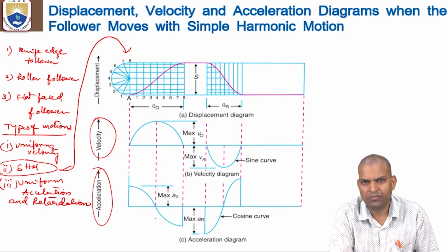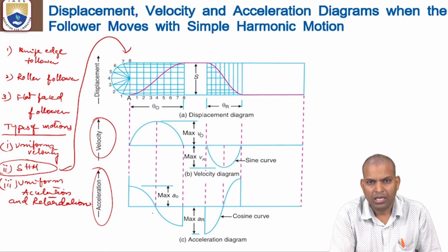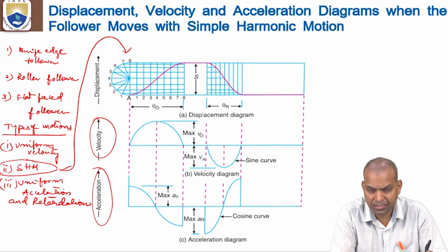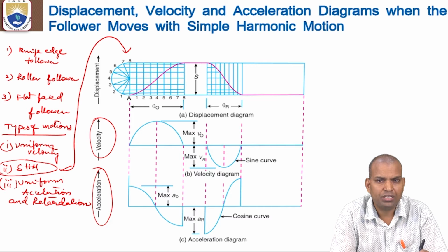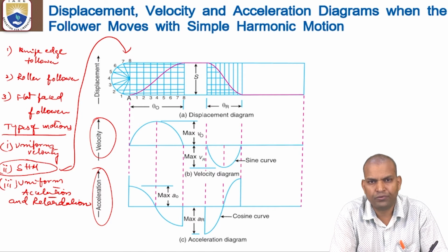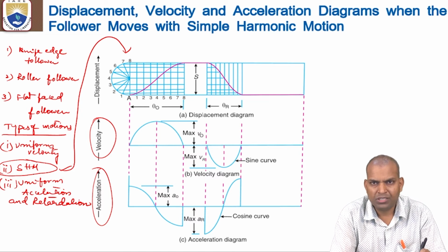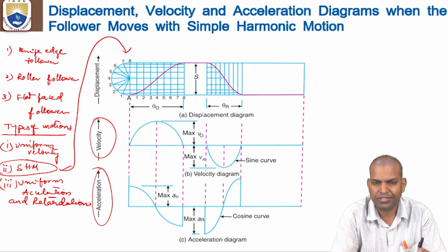What is the velocity, what is the acceleration, and these velocity, acceleration and displacement diagrams are in relation to the angle of rotation of the cam. The angle of rotation of the cam is in terms of degrees. Here we are going to show what the displacement diagram is.